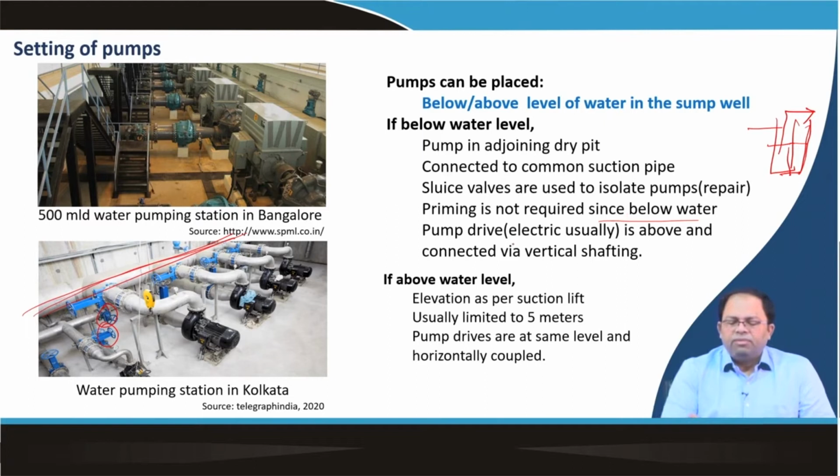And finally, the pump drive. The pump is there, but there is a mechanism which does either rotation or some sort of movement inside the pump, and that particular mechanism or motor could be an electric motor, or it could be a fuel driven motor, whatever the case may be. This drive is actually at a higher level. It is not put inside along with the pump. Sometimes it may be put there, but it is usually kept outside or at an above level, so that the chances of flooding and all are minimum.